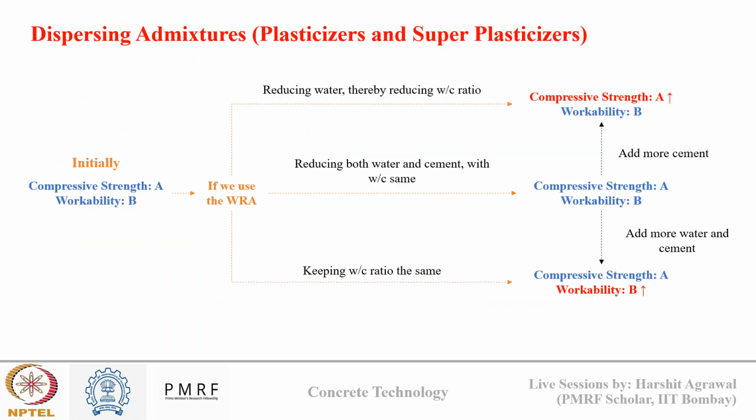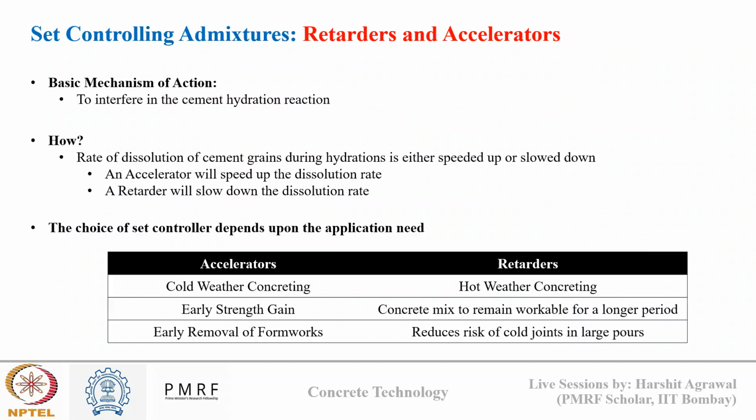Then we discussed in detail plasticizers and superplasticizers: what they are, their chemical composition and how they cause dispersion in concrete, either via steric hindrance between hydrophilic groups or due to electrostatic repulsion between cement grains with high zeta potential. At the end, we saw what domains of application a water reducing admixture has, either strength increase or workability increase or cost decrease.